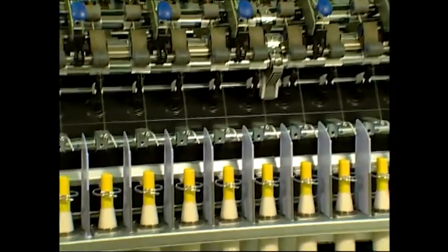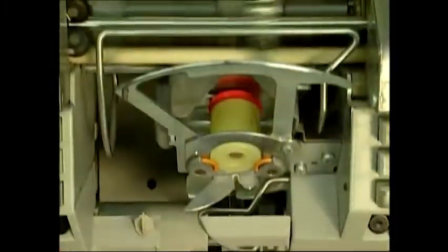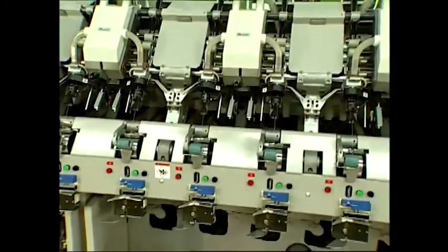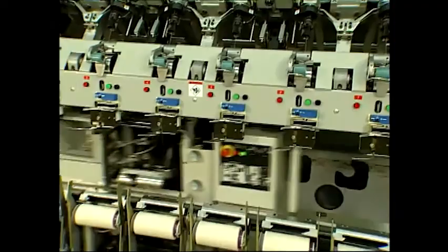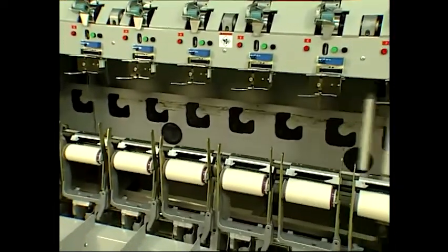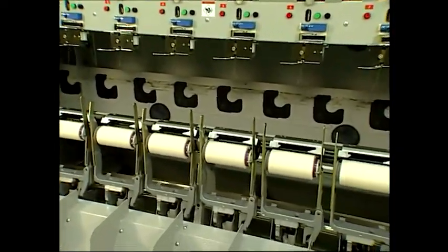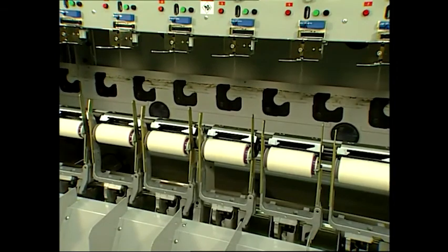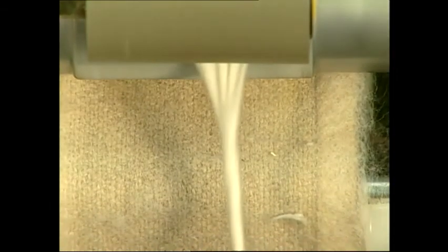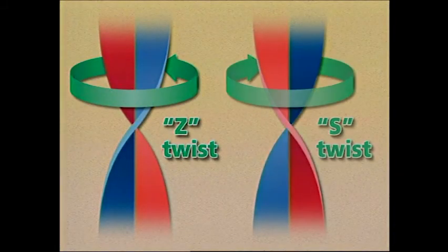Yarn type means either ring spun, open end, rotor spun, or air jet. The yarn type has an impact on skew, appearance, strength, hand, and has a marginal influence on shrinkage. Twist direction refers to the spiral twisting of fibers during yarn formation and is either Z-twist or S-twist.